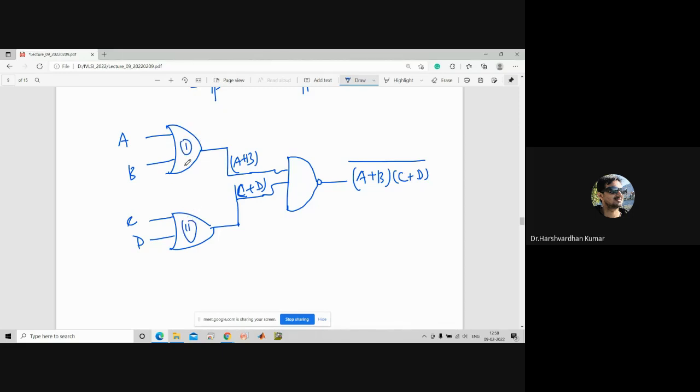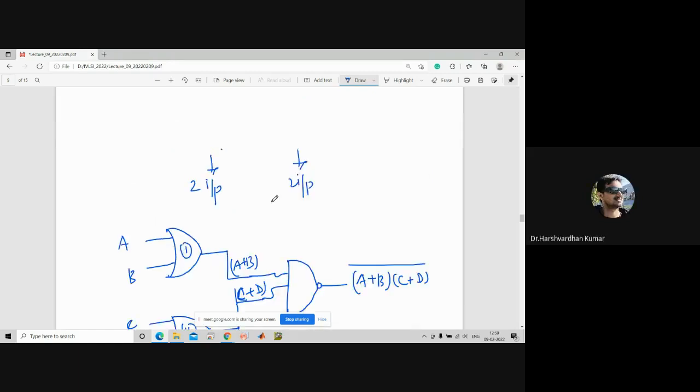So the first OR gate, this is 2 input, right? So for the 2 input, how can we design the first OR gate using the CMOS? The CMOS should be connected in, yes, in parallel, right? For an OR gate, we connect the transistors in parallel. Okay. And for the AND gate, series. So here, based on the above fundamentals, we will connect.